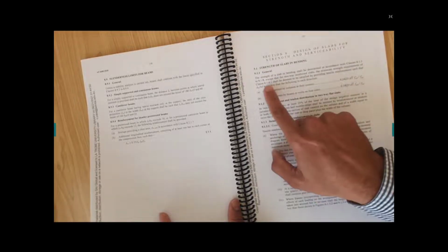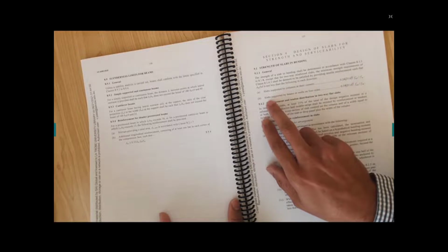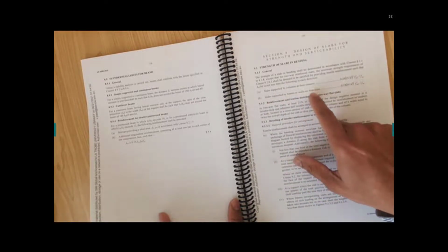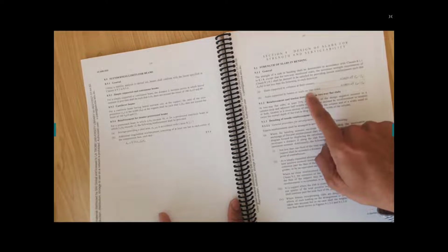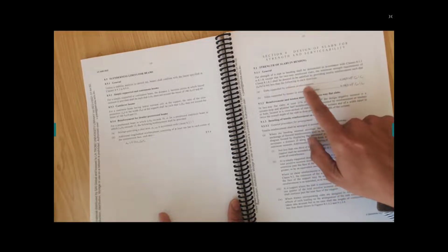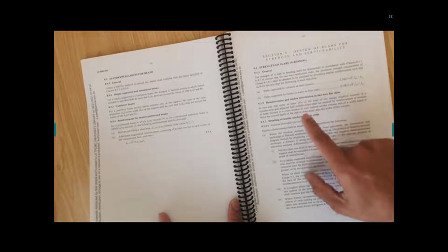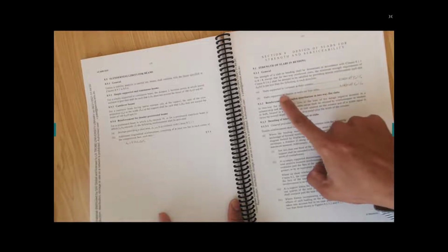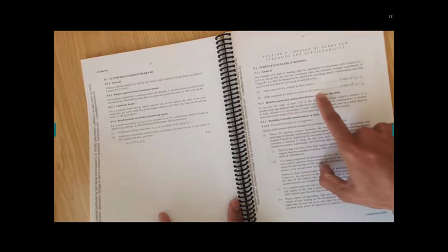Bending, because I think they mention somewhere here a slab supported by beams and walls on the 4 sides, right? You can see, you can't use this one for one-way slabs, or this one you can use when supported by columns at the corners. But here we're going to use this one, not this one, because our slab is supported on 4 sides.